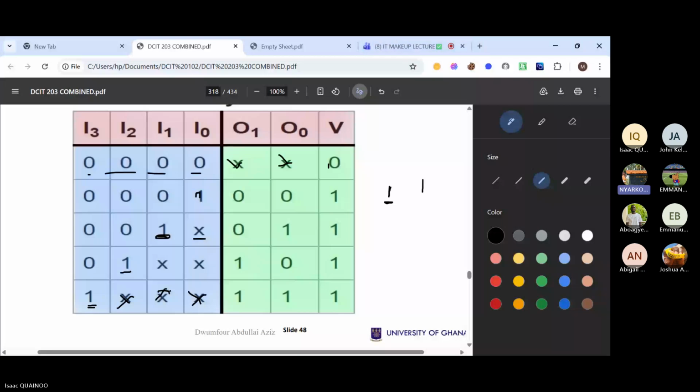So all the X over there represent the don't care. Exactly, don't care. That means you don't care what our input there is. Our input can actually be 1. We don't really care, but the corresponding binary value will not change. Because we know that our input here is 0, 0, 1, and then a don't care. So in this case, the first one takes priority. Anything that follows, we don't care. Even if this can be a 1.